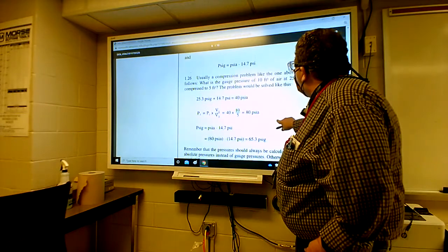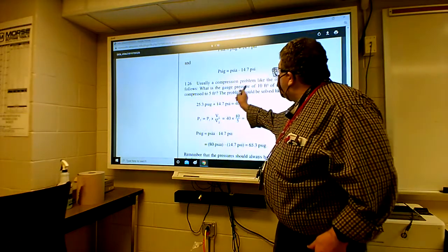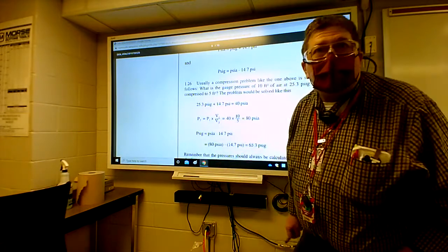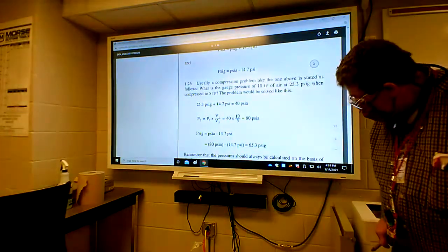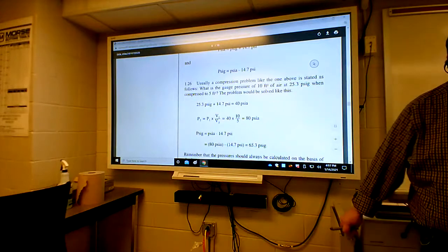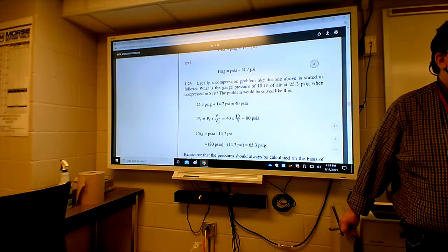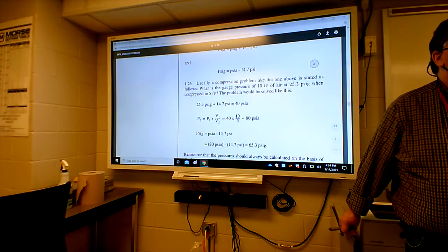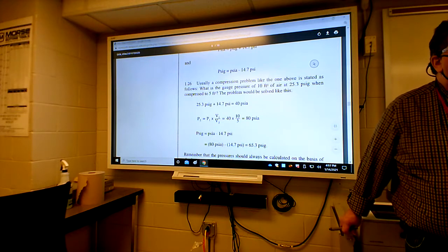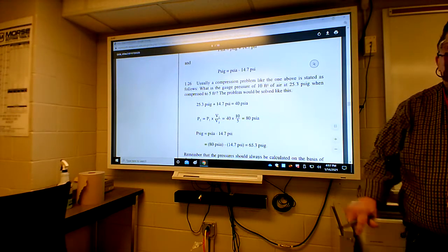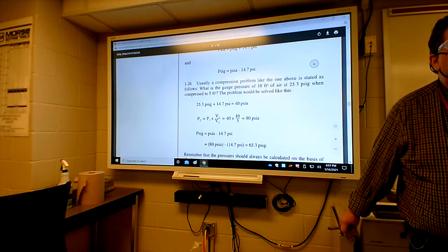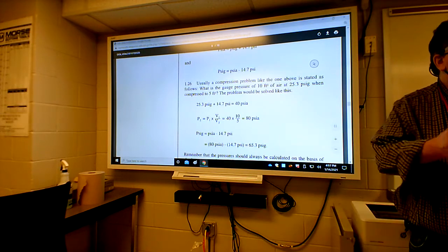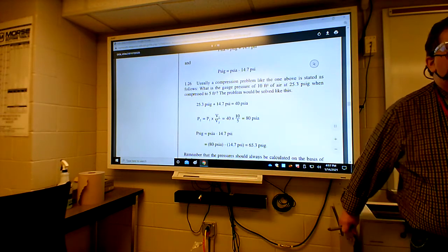So you're going to start out by converting the 25.3 over to absolute pressure. Now, we'll say this for any of you that are going to be taking refrigeration classes, or if you ever get into ammonia refrigeration: in the refrigeration world, you do have to do what we're talking about here. You have got to convert things over to absolute to do calculations. It's a normal part of refrigeration.